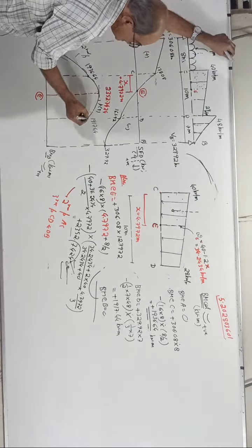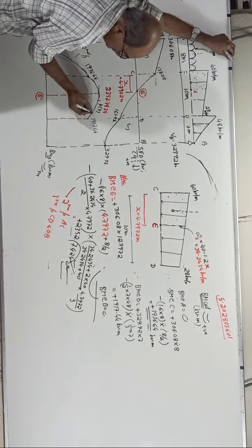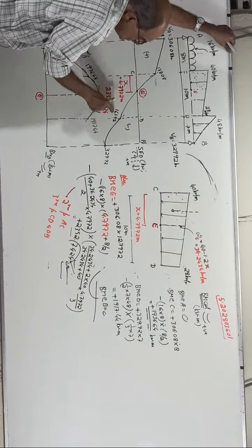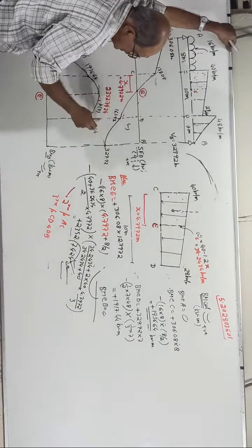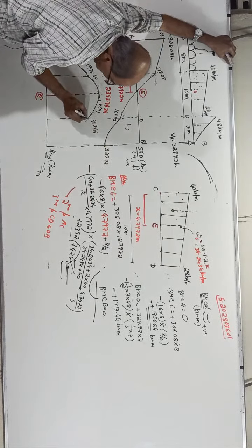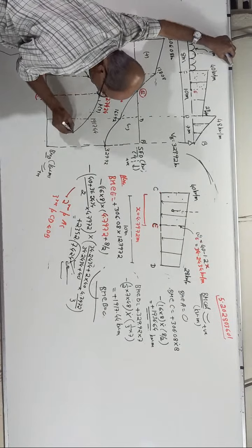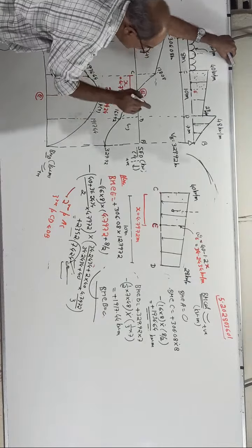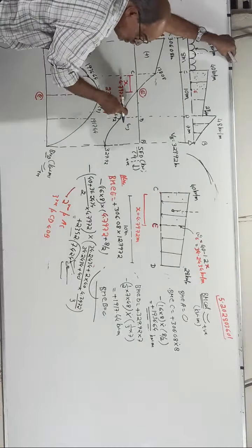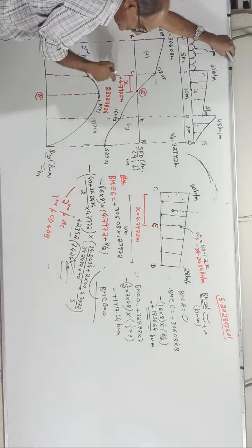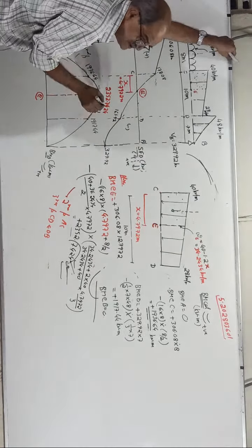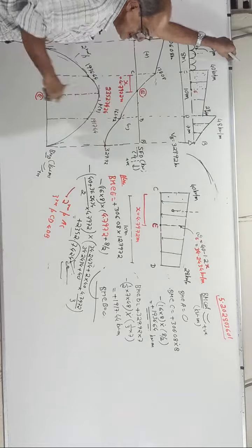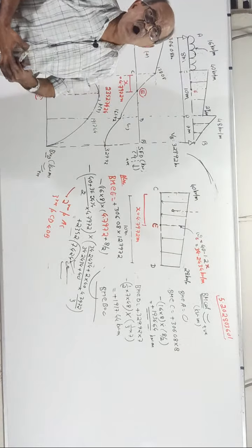Now, when you come to the end point of D, the slope of the tangent here should be the shear force for this side, 161. The shear force for that side also is 161. So this second degree parabola should come this way, so that the tangent will be common for both. That is because the end of the parabola's slope and the start of the next parabola, this is third degree, that second degree, share a common tangent, the same slope. And here the slope is high. Why? Shear force is 329.92. I explained all this earlier.